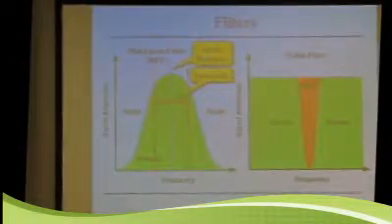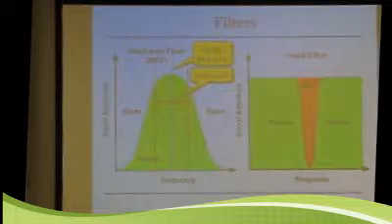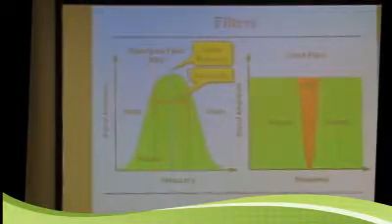So remember, we want to make sure that our signal is only of a certain bandwidth, so a band pass filter can help us with that. As we talked about, let's say this is 3.8 megahertz, 3.9, and 4.0, 80 meters. Okay, your signal is actually about how wide is a single sideband signal? We had that last week. Anybody remember the number? 3 kilohertz. So your signal is maybe that big. So let's expand that. And so your signal is this big.